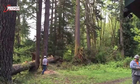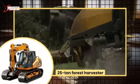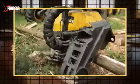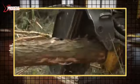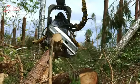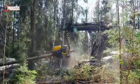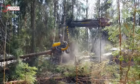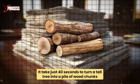Selected trees are felled in a controlled manner. This process is carried out using a 25-ton forest harvester. The cutting head grips a tree with a lathe-like device, and a saw just under 1 meter in size cuts the trunk. The felled tree passes through the head, where 4 blades cut off its branches and the saw cuts it into more manageable pieces. It takes just 40 seconds to turn a tall tree into a pile of wood chunks.